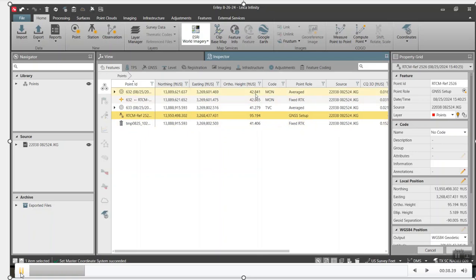I just want to show you how important getting the right geoidal model is. Right now in Houston, if you're comparing Geoid 18 to Geoid 09, you could see anywhere from 2/10 to half a foot difference, and that's why it's important to know you have the right geoidal model. So let's show you how we have these geoidal models and how we can transfer them to an SD card to get them onto the data collector.